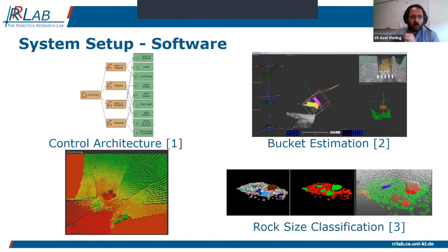And the last thing which we used is the 3D surface map. This is more or less the sensor data of the 3D laser scanner put into a grid map. Of course, this is then dependent on the current position of the laser scanner during the excavation process and therefore also the boom. What we can see is that the green points denote a higher value and the red ones denote a lower value. And this is what we want to use to really estimate what has been removed.